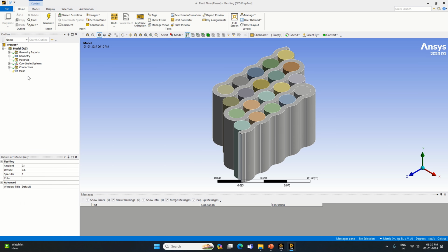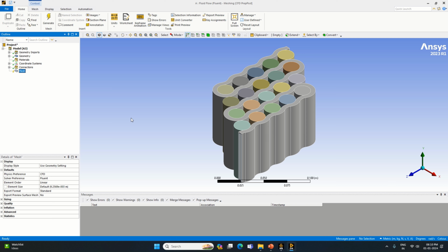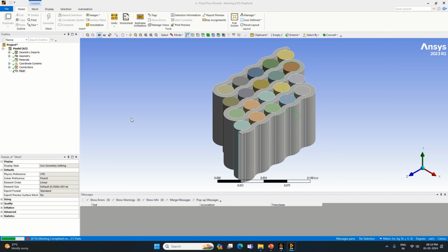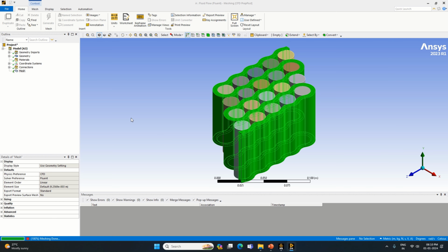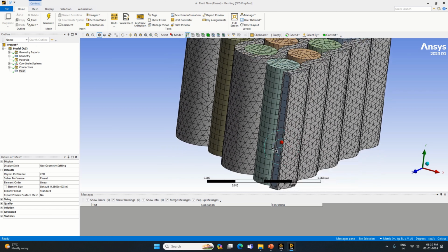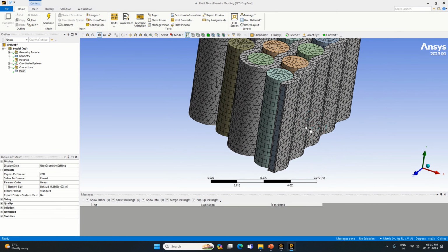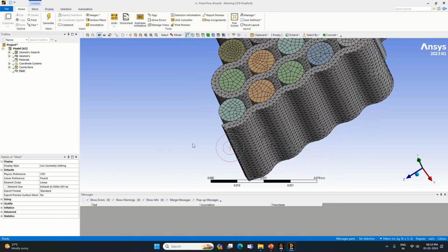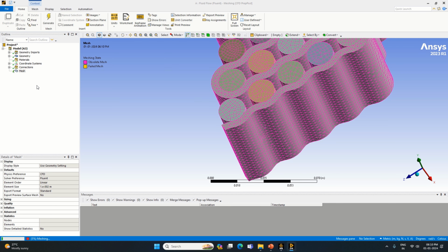Okay, so we have the mesh here. Let's click on generate. So the default mesh will be generated. Depending on how good the mesh is, accordingly you may modify the mesh size as well as the element size which has been here. So this looks to be not that great because this is a channel through which the fluid has been flowing. So we definitely want comparatively finer mesh on this region. So what I will do here, I will just check the statistic here, only 54,989. I put it 0.01 as element size, and let's make it generate.